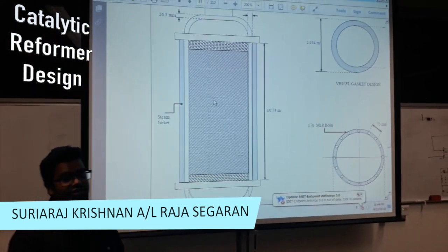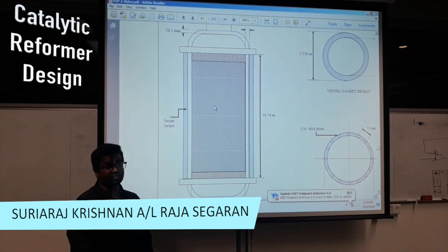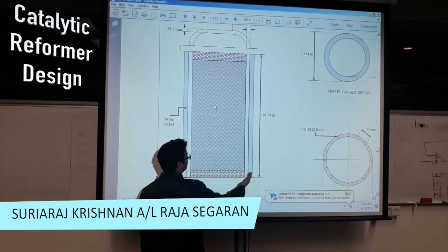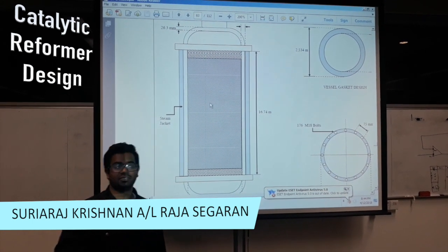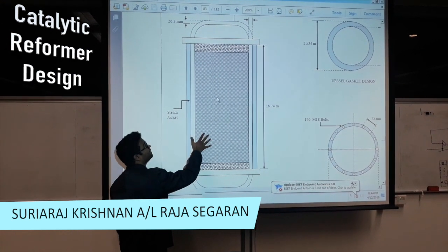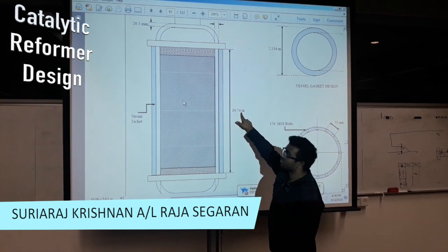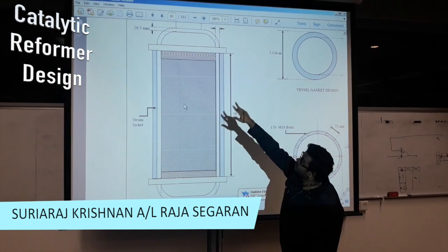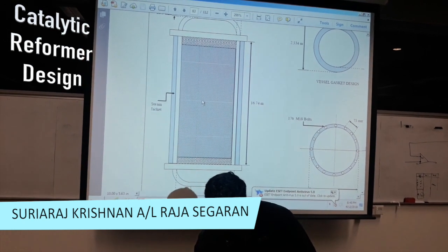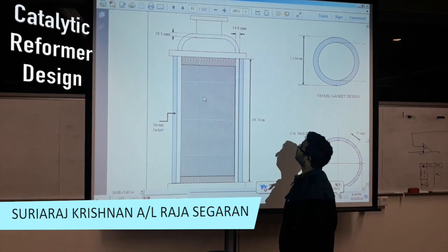As you can see, because the reaction is happening at an endothermic condition, we are using a steam jacket around the reactor for continuous heating. And this is the catalyst bed, and the length is about 16 meter, and the thickness of the wall is about 14 millimeter.